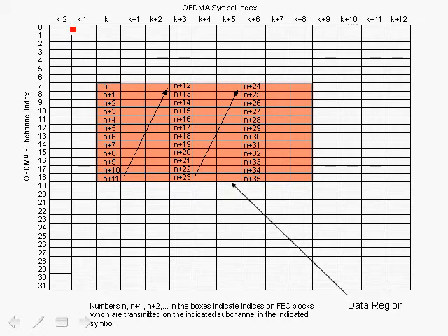We also have the time slots, which are per OFDM symbol, and within this grid we can define a data region corresponding to a data burst. The data region is defined by a subchannel offset and an OFDM symbol index, or a slot time offset. The number of OFDM symbols and the number of subchannels constitutes then a data region.